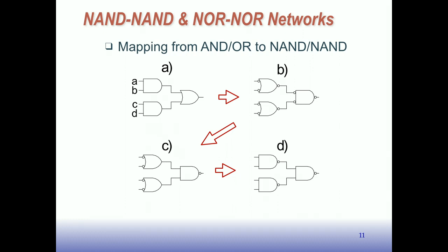Now, as I said, if you were going to implement this with transistors, you probably wouldn't use ANDs and ORs, because an AND gate is 6 transistors in CMOS, and a NAND gate is only 4 transistors. So we like to convert everything to NANDs. Here's the little procedure on how to do that. Once you know it, you can just skip all the intermediate steps, but just so you can see how it works, what we do here is introduce bubbles.